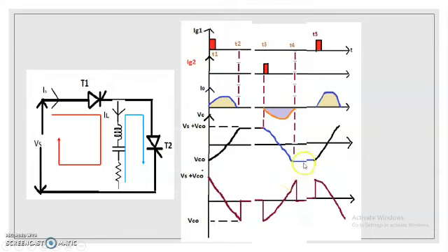The capacitor will be retained with the value that it was carrying at the instant when thyristor T2 is turned off, that is Vc0 in the reverse direction. Next, VL, the voltage across the inductor, immediately becomes 0 because the current is 0. Now, the next thyristor T1 will turn on only at the time T5.